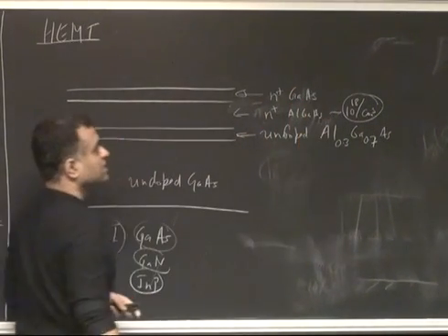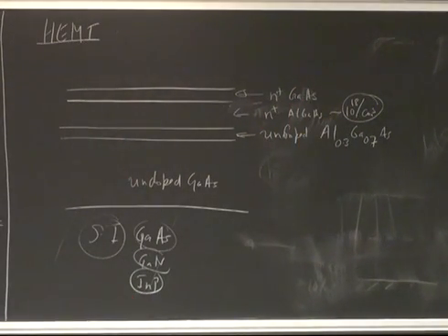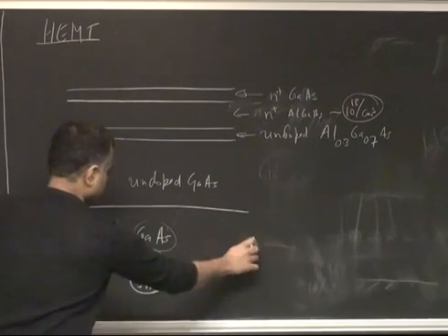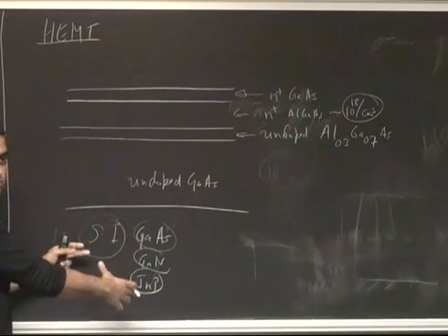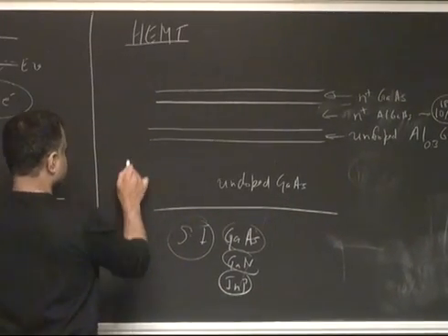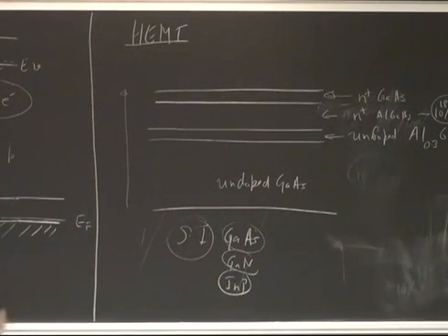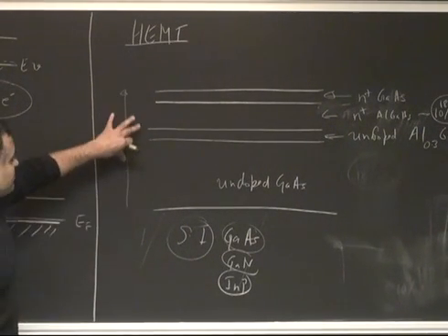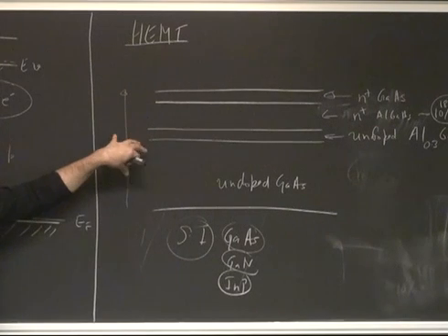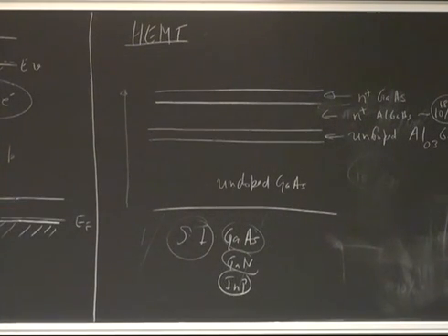N+ gallium arsenide. And there's a purpose for each of these layers. There's a reason why each of these layers has been grown that way, and we're going to dissect that right now. I already told you the reason for the insulating layer. This layer you can buy in the market today, maybe a 4-inch wafer of semi-insulating gallium arsenide. You put it into the MBE system in Phillips or Duffield and do the growth. Many of the initial HEMTs, in arsenides as well as gallium nitride, were done in Phillips Hall here, so a lot of the early papers were work done here at Cornell.